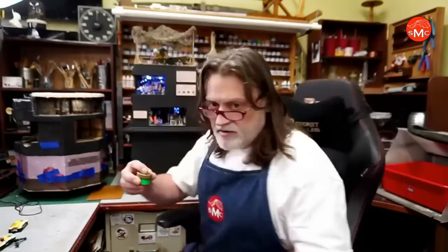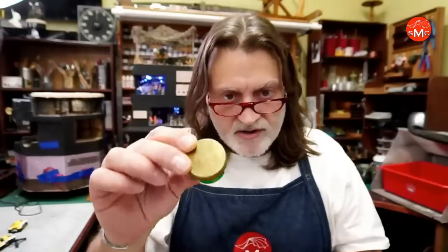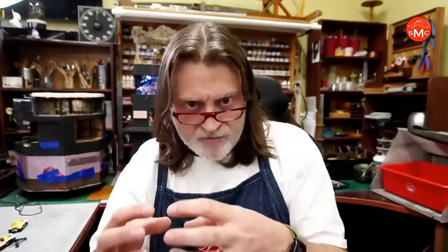but it's going to hold together through handling and moving and stuff like that. If that's not enough, if you really want to glue this sucker together, then what you do is prior to doing the CA glue, use a little bit of baking soda. So baking soda, and you combine the CA glue with it, bang, it just goes rock solid just that quick. So that powder becomes structure, and good structure. It's not just like glue. So that's one thing that you can do.